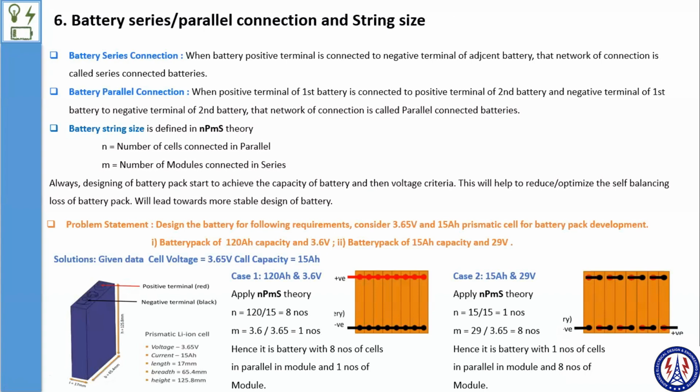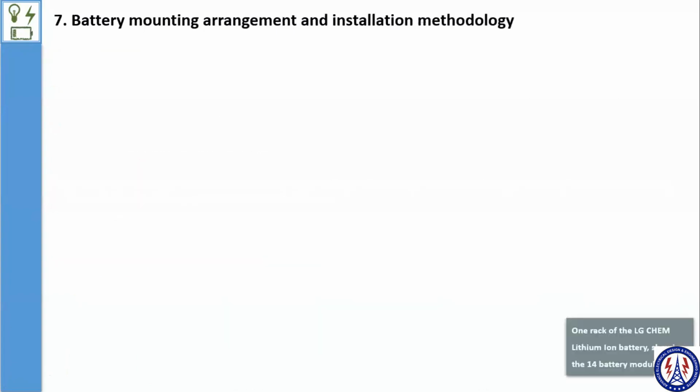A series parallel connection would be impacting your battery voltage level and according to your battery capacities. When you are going to try for multiple batteries having the same voltage and same AH capacity, but the chemistry would be different, then your count of the cells would be different, right? That affects your cell level performance, like particular cell level voltage and cell level AH capacity. That matters when you are trying to calculate your number of cells.